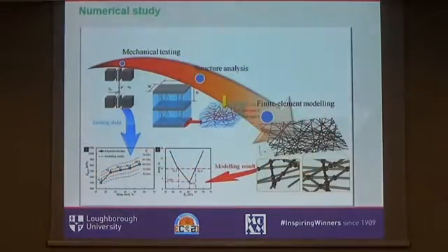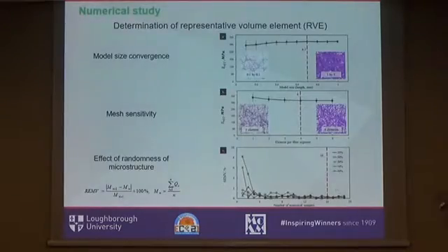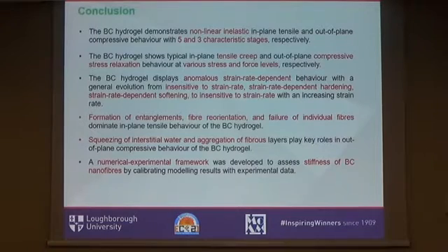Very quickly, in order to model this material, you can do a continuum approximation, but you need to introduce a discontinuous approach. We have done this, and we have obtained some of the parameters. I'm aware that I must finish. The idea is just to give you a flavor of how complex materials can be, and how tricky they are in their behavior. An interesting point to remember is that materials with fibrous networks without a matrix demonstrate negative fracture toughness. If you want, they become stiffer when you introduce notches. And that is it. Thank you very much.